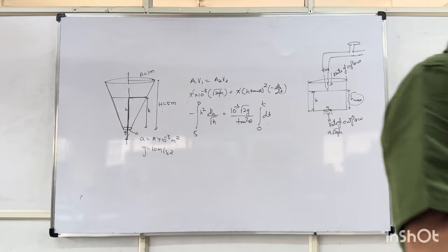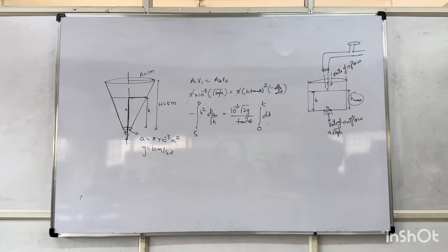You have a container, cylindrical container, in which there is a small hole at the bottom. So, you know the velocity of the flux. Yes or no? What is the velocity? Root over of 2gh. Fine. We are all happy about it. So because of that, if the container is on a smooth surface, it will keep moving backwards because of the acceleration called thrust force. How much is that thrust force?